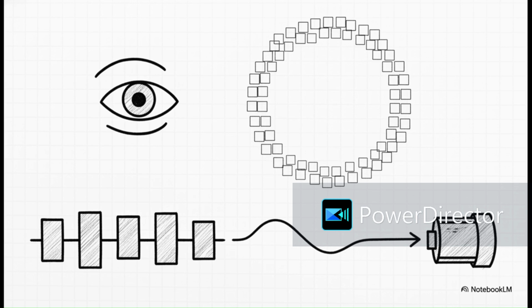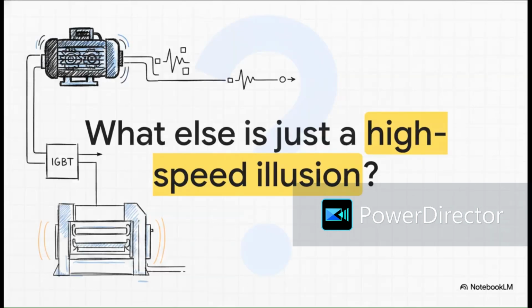The VFD's rapid square pulses are fired so incredibly fast, and the motor's own inductive properties naturally act as a filter, that the motor is effectively tricked. It sees a generalized average sine wave. It acts exactly as if it's receiving a smooth AC curve, which is what allows it to run so seamlessly at that customized RPM. When you frame your answer this way, starting with the real-world industrial need, explaining the IGBT switching speed, nailing the PWM concept, and finishing with that square circle illusion, you leave absolutely no doubt that you understand this technology inside and out.